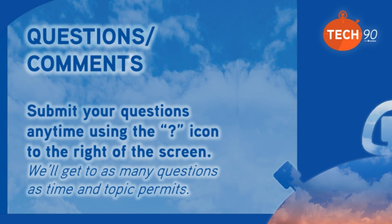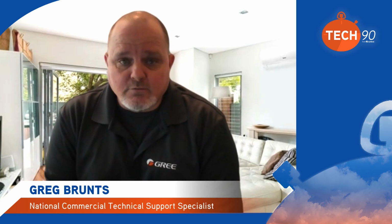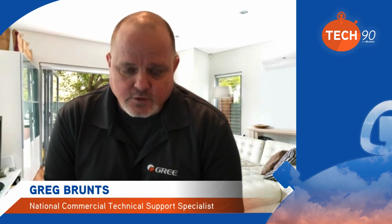This one came from Joe. Joe asked, so you do not recommend using press fitting at all on installs? That's not exactly what I said. I don't recommend you cut off flare fittings of GREE's equipment and use a press fit.